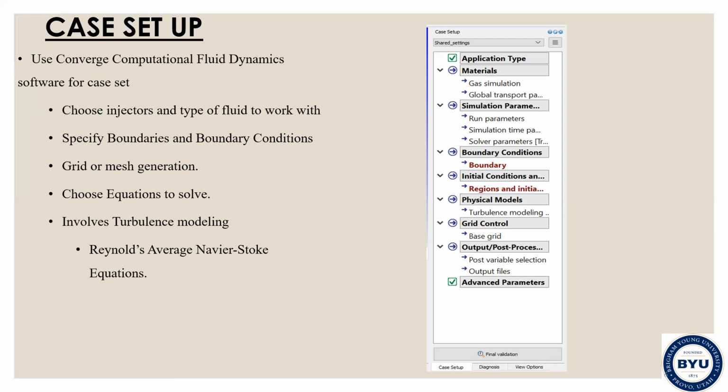One of the most important things in my case setup is my grid or mesh generation. With this, I am breaking the whole geometry into smaller elements, on which the governing equations that I'm going to choose to be solved are applied.